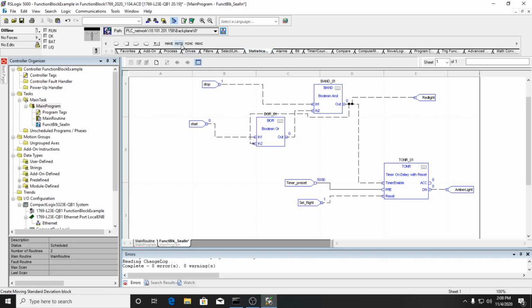You can do a lot of different math. There's a moving average and just a lot of different other terms and min-max values here. Of course, you always have functions for alarms, some one-shots. Okay, so if you need one-shots, timers, we already kind of discussed. You have your normal timers available to you.